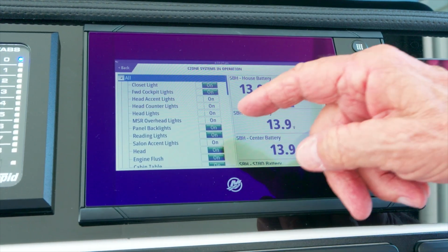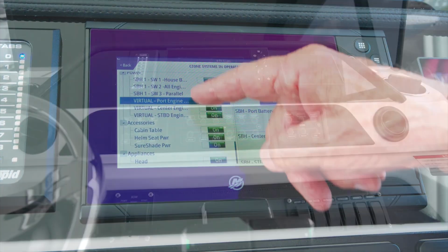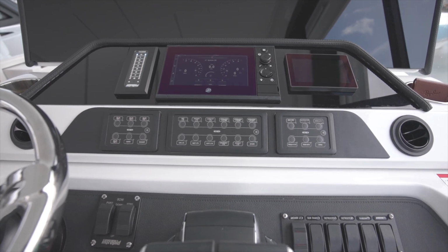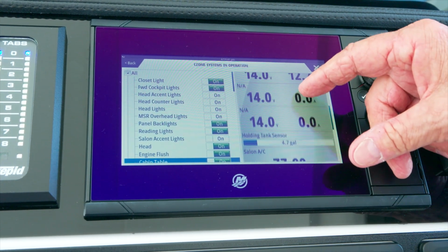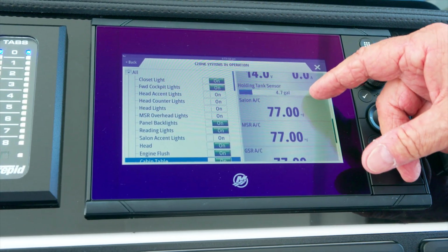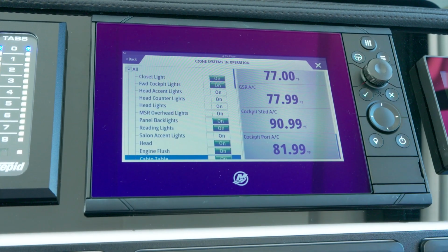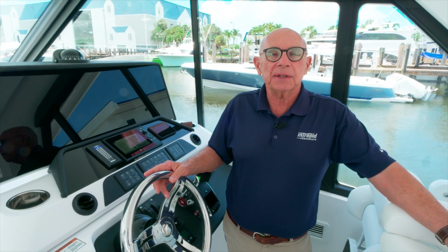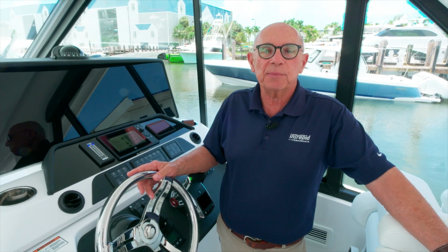You'll pull that up and that'll show you all the systems that have hard buttons that are available, such as the ones that are beneath this C-Zone display. This also gives you your battery readings, what's doing with your battery chargers right now, temperatures in the various cabins, and a host of other information. There are 3 panels installed below the vessel view that allow you to use the appliances that are connected to C-Zone just using a hard press button.